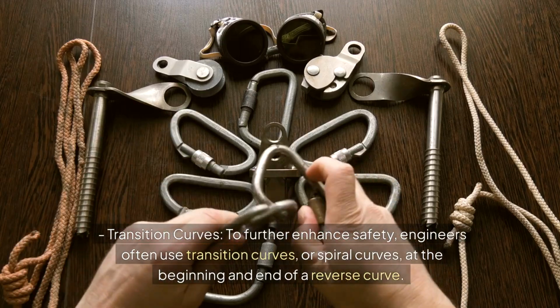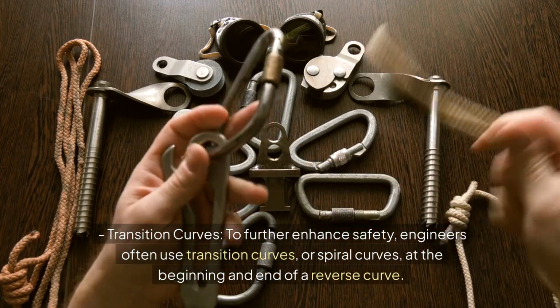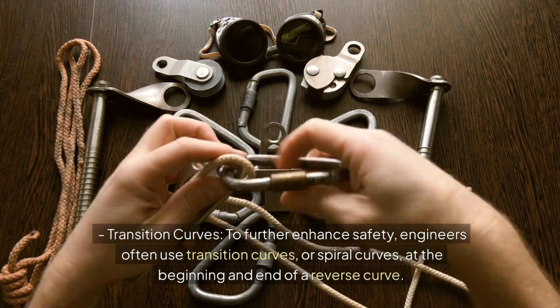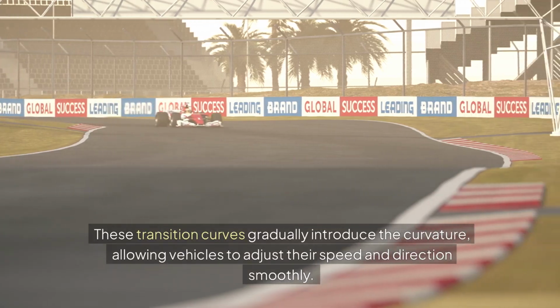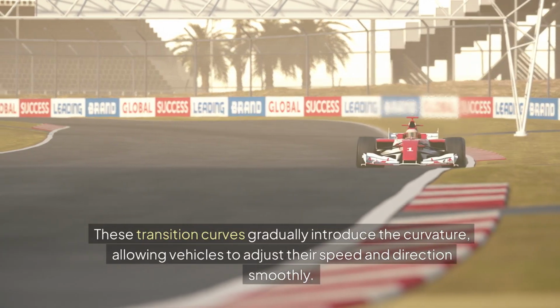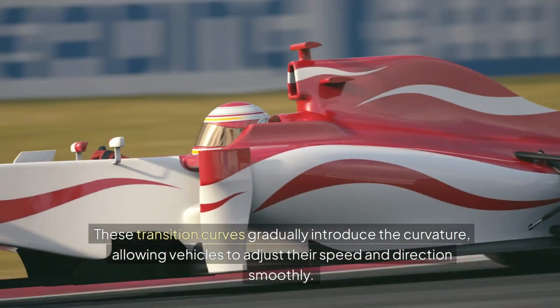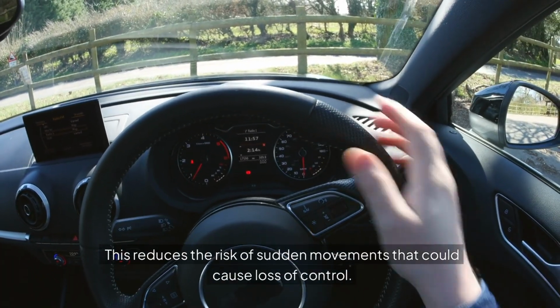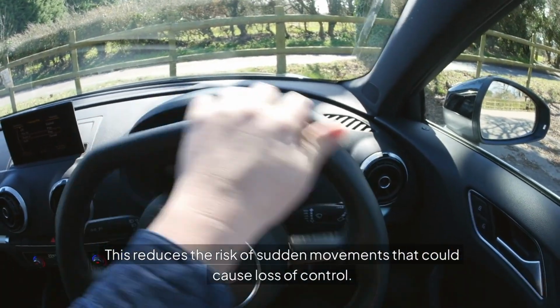Transition curves. To further enhance safety, engineers often use transition curves, or spiral curves, at the beginning and end of a reverse curve. These transition curves gradually introduce the curvature, allowing vehicles to adjust their speed and direction smoothly. This reduces the risk of sudden movements that could cause loss of control.